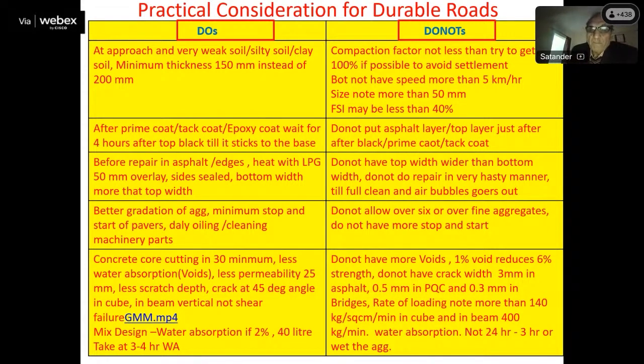If you see today, all contractors are very good contractors. They are working for a longer period. Why is failure there every time? Why every time is there failure in RE wall, bulging everywhere? So now we have revised the code. Earlier, what was written, in place of filter media, you can go for geocomposite. Even in reinforced GSB also, most of the contractors have started using geotextile in the GSB, geotextile in the WMM, and they are reducing DBM. The roads are not surviving for a longer period.